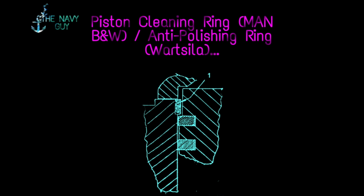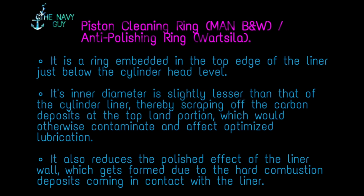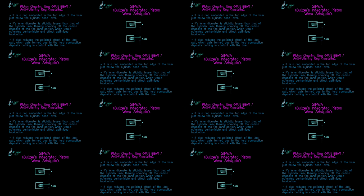Anti-polishing ring, Wärtsilä. It is a ring embedded in the top edge of the liner just below the cylinder head level. Its inner diameter is slightly lesser than that of the cylinder liner, thereby scraping off the carbon deposits at the top land portion, which would otherwise contaminate and affect optimized lubrication. It also reduces the polished effect of the liner wall, which gets formed due to the hard combustion deposits coming in contact with the liner.